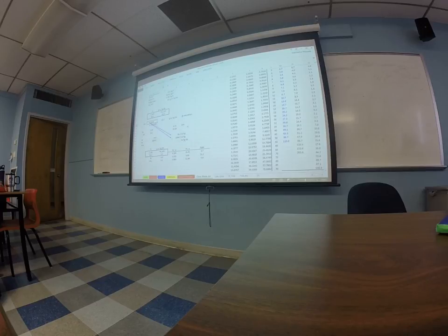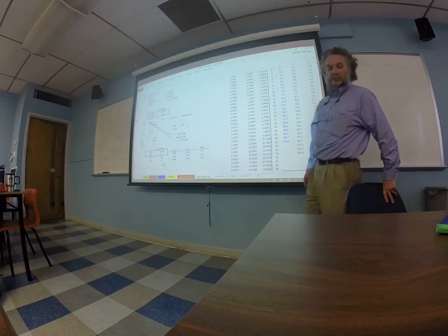Is that? Not wait for the green ones yet. No, we haven't gotten to the green ones yet. Now on the other hand, these two here come from the temperature that we have there. If I trace the dependence, they are these two cells here. These two cells are the exact same enthalpies, but calculated using the dry bulb temp. So those are the enthalpies that correspond to the dry bulb temp. So when do we have the same enthalpy? Only when the dry bulb corresponds to the wet bulb.